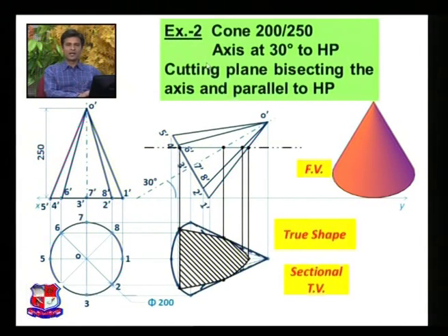So you should take care about the insertion of the dimensions at least once in the diagram, so that it could be easily redrawn by anybody. For example, this height and this diameter should be represented in the first drawing, then this angle should be represented once only. Here it is not needed to represent the height or width of this triangle.